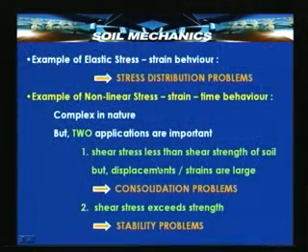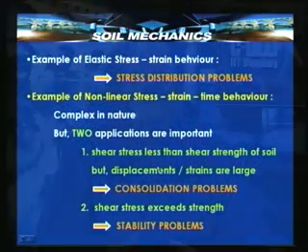One is when the shear stress imposed on a soil due to a structure is less than the shear strength of the soil, meaning the soil does not undergo shear failure, but the displacements caused by the stresses or the strains caused by the stresses may be so exorbitant that although the soil does not undergo a stress failure, it undergoes such a large strain that it is equivalent to failure.